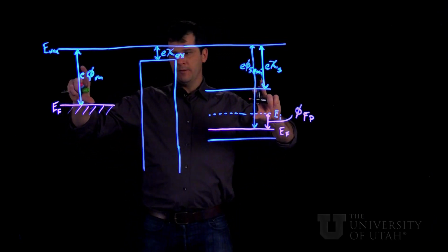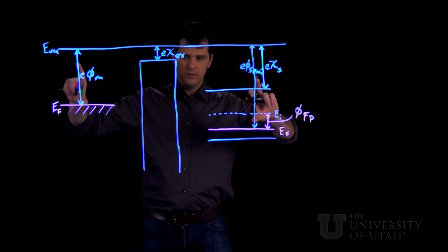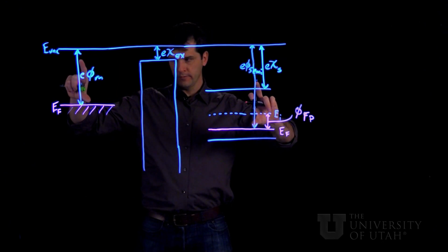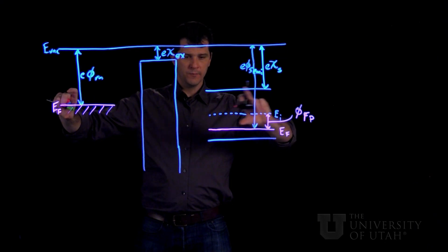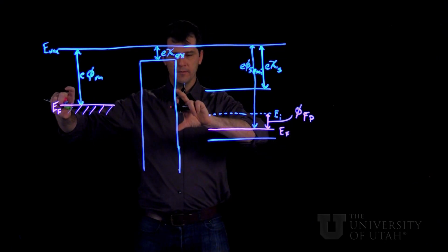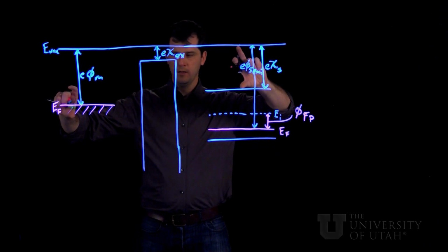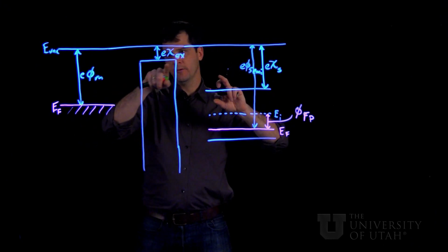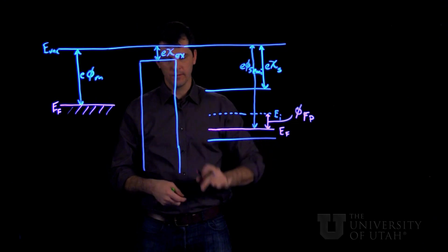So the built-in voltage here is, like all junctions, going to be determined by the difference in Fermi levels, or the difference in work functions, really. So what we have to do, if we clamp the metal, we have to imagine sticking the band edges of the semiconductor onto the oxide and then pulling up until the Fermi level becomes equalized. And what that's going to do is it's going to drop some voltage across the oxide, and it's also going to induce some band bending in the semiconductor.